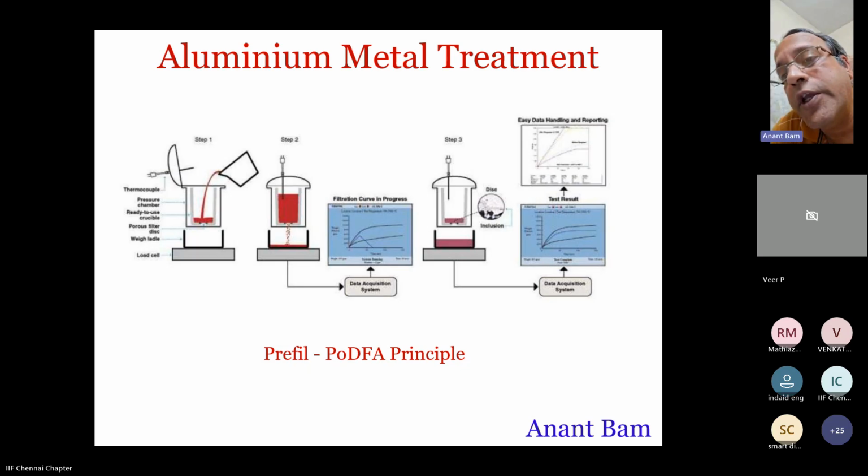That's the fourth image. The vertical section of that sample is seen under the microscope. The number of inclusions seen above the filter is 10,000 times more than in the actual metal. So you get a quantification of that.